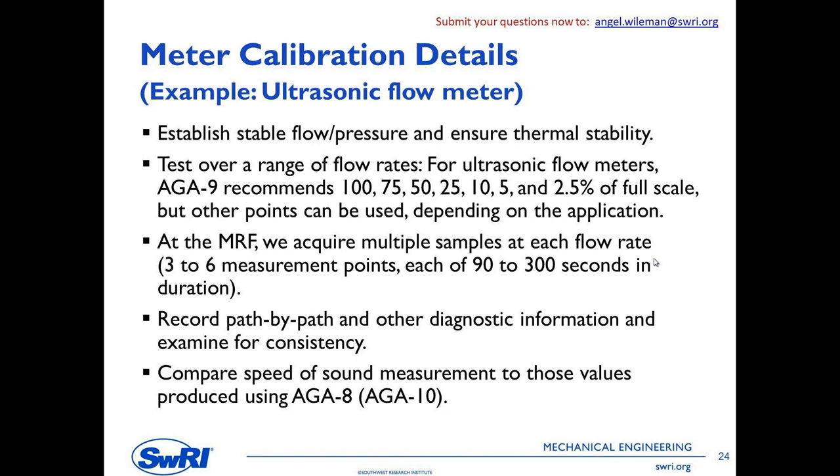With any meter type, what you're going to do after the meter is installed and ready to go, all the calibration facilities are going to do this. They're going to start the flow up. They're going to flow through that meter at whatever pressure and temperature condition they're going to test at. And they're going to do that for long enough to ensure thermal stability of the meter, the pipe, everything around it. That tends to be one of the longer parts. Getting ready to test is just waiting for things to kind of settle in.